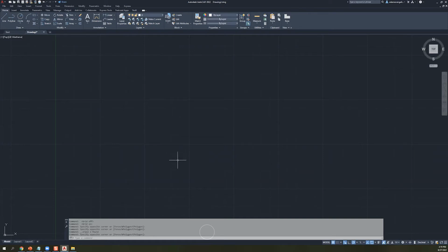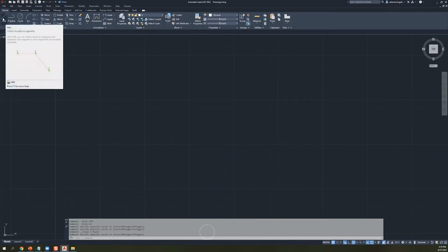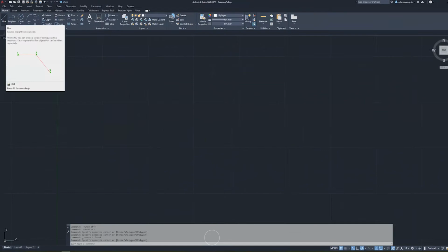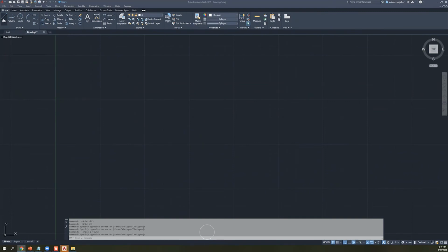Okay. So I think to start, let's go back to the line command. Again, you could start this line command like 10 different ways. I'm just going to click on the button up here. If you mouse over any of these commands, it will give you a preview along with some notation that'll make sense. So this is literally just 1, 2, 3 clicks, and you could make your lines accordingly. You also notice that there is this small little symbol down here with this yellowish window. I'm not sure what to call that really. If I have to pop up again.